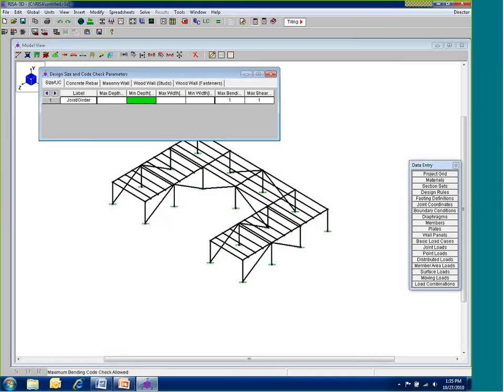But let's say that this is a platform that we don't quite know what we're going to be doing yet, and we've only got some information on a little bit of the loading for the equipment, but I don't really know properly what the full loads are. So I'd like to design it to 90% of the bending check and 90% of the shear check, so we don't go to the full extent of what we've got there. Then I'll give myself a default, so I have a joist girder rule and a default. That will allow everything to go to 90%. The rest of the model will be at 90%, and we'll just call this all. So everything else will be all, and then the joists and the girders will be that.